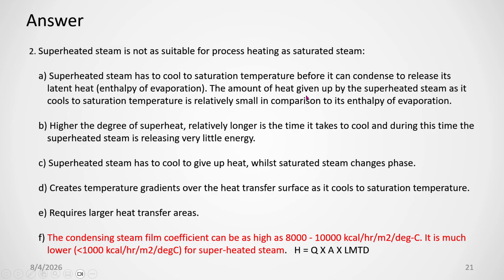The latent heat is very big, but the heat from the superheated steam is a very small amount, and it will take a long time to reach dry saturated steam. The higher the degree of superheat, the longer the time it takes to cool, and during this time the superheated steam is releasing very little energy.